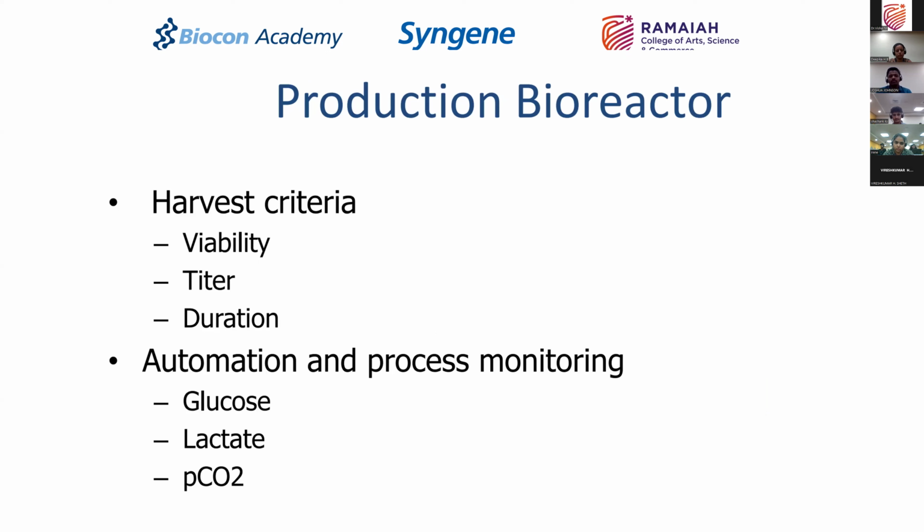Now, production bioreactors, you also need to understand the harvest criteria. What is the viability of the harvest? Are you sending it to a centrifuge, depth filter, etc.? What is the duration in which you are going to complete the process? So, when do you stop the process of fermentation? Is it 5 days, 2 days, 1 day, etc.? And what is the growth factor, the cell density you are targeting? Is it 1 gram per liter, 2 gram per liter at the end of the day, of the cell that you're talking about, and even more, is something that you have to determine to say when will you start the production bioreactor, when will you end the production bioreactor.